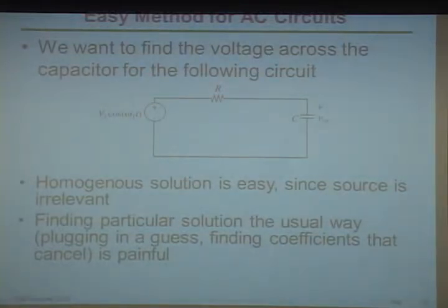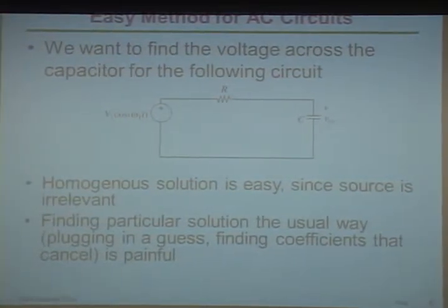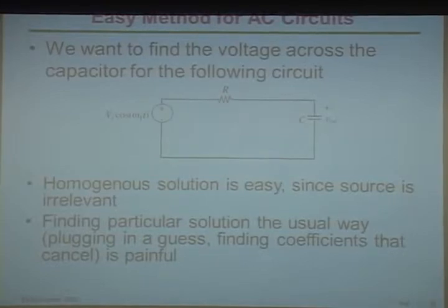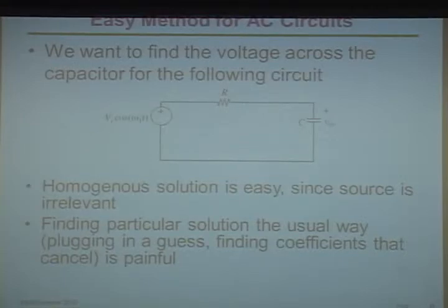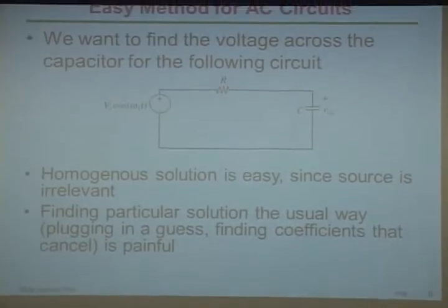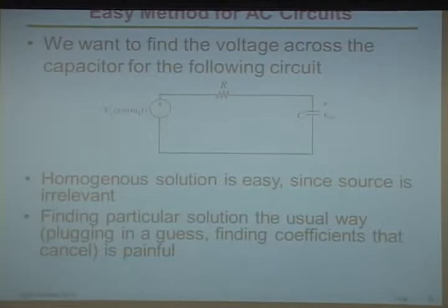They're useful for filtering. We haven't talked about that a lot, and that's what we're going to talk about more today. And they're also useful for modeling parasitic capacitances. This is the case where, for example, with the gate delay thing I was talking about before, in a circuit you can model the time it takes for a gate to respond by capacitances.